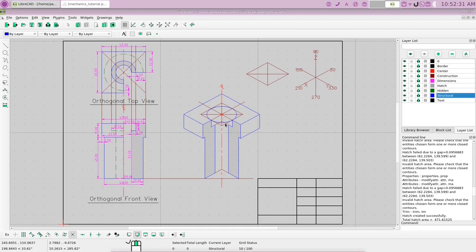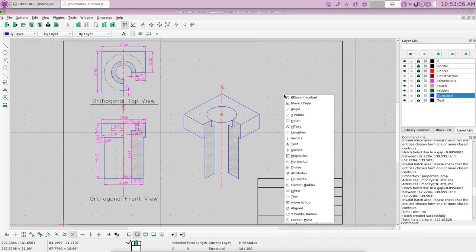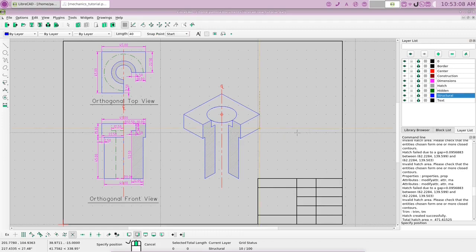Now, we need a circle down here, 7.5 lower. And in order to get that, what we're going to do is we're going to turn off the construction layer for a minute so we can see what we have. Okay. Now let's take and move this point down 7.5 units so that we can put another circle in there. Okay. So let's draw a line just to get a point 7.5 units lower. Okay. So let's go with a vertical line, and let's make it a length of 7.5.